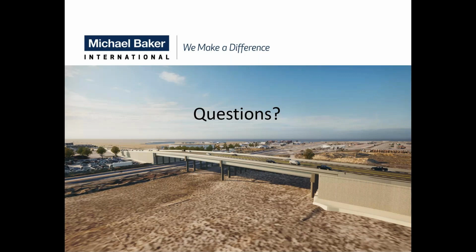And so there definitely was some, we had to work through that, and that's where we had to balance out where we had more piles, especially with the column height differences as well. Another solution would have been to use a two span steel girder bridge that would have just one pier or bent in the center. But this worked out to be the most cost effective solution for this project.